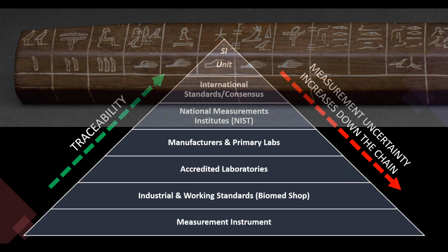The main thing is making sure that what you're looking for and what you're going to use it for matches the specifications, and that it's got that function and the accuracy you need. What I also recommend, if you are going to get a multimeter and a separate PRT, is to send them in together and ask the lab to marry them together, because they can do that. They can actually chart it out, and they can give you a better calibration if you send them together and say, hey, I want this probe married to this multimeter, and get them both calibrated.